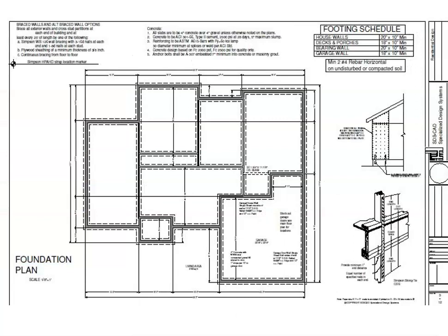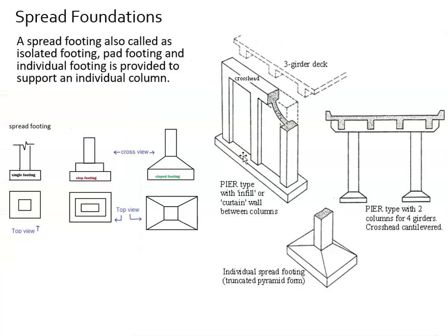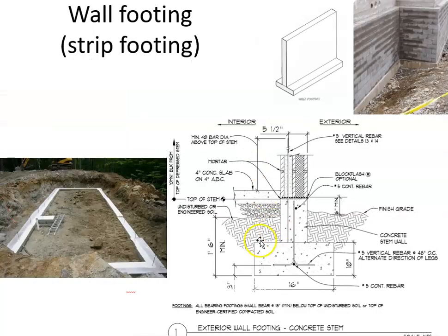And then what these often look like in plans for all projects, despite the scale, is typically how they're depicted. So footings are typically always drawn as dashed lines. So we're down here in what we call the foundation plan. So we see the foundation walls, however high they are, doesn't seem to be indicated right here. So this is the footing sizes. So again, those are the dashed lines. So we have wider footings. We don't see that. We see that right here, right?